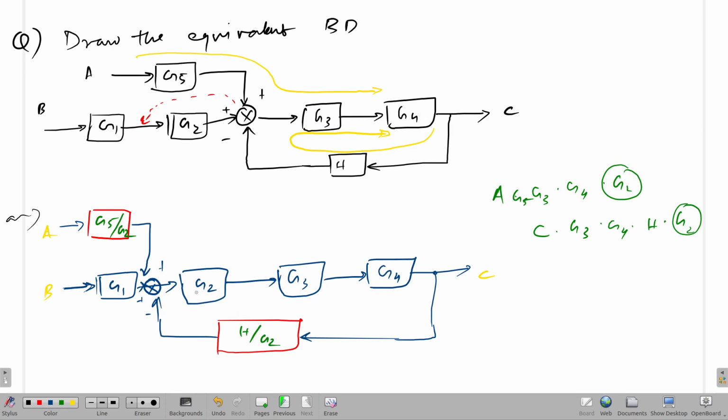So you have seen how to change. So this is how you change the blocks in the branches, not the main path, the branches, depending on what the shift is. Okay, here because we are adding a new block into the path of these shifted blocks, you have to cancel for that. If you are shifting this forward, you would have to multiply it with G3 because you would have missed G3 which was there in the initial path. So this is how you shift.